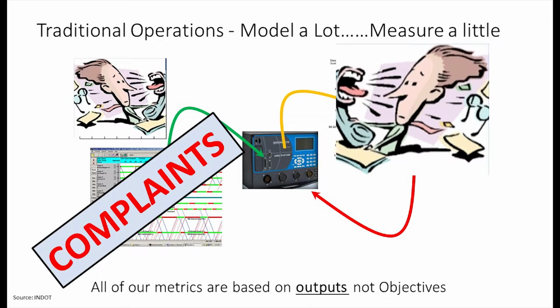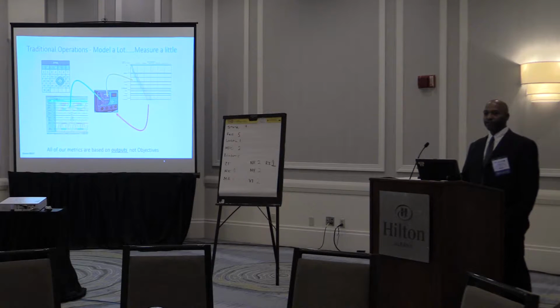If we want to evaluate that, as I said, we'll do a before and after study. Typically, this is a manual floating car study where you're measuring travel times. Some of this has been automated now, and some agencies are using probe data. As an outcome of that, we'll go back and tweak the timing at the intersection. If it's not working consistently with what we planned with the time-space model, we do the floating car study, so we may go in and make a few tweaks. That's the traditional process, and this happens maybe every 3 to 5 years, which I think is considered best practice.